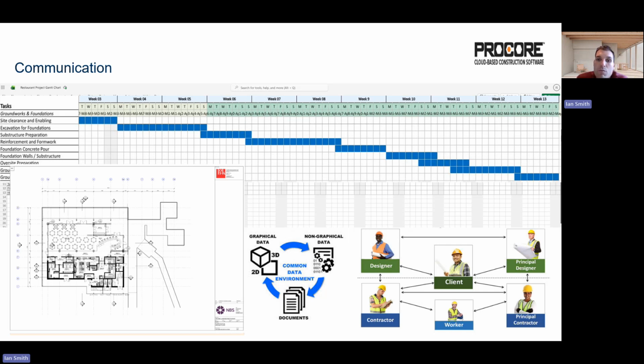We'll also need to communicate resource requirements and delivery schedules for construction activities such as concrete foundation pours or drainage installation, as these rely on materials arriving at the correct time. By communicating delivery schedules to suppliers and site teams, I can ensure that materials are available when needed and the storage areas on site are organised effectively.